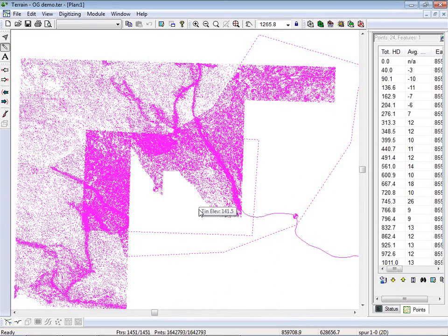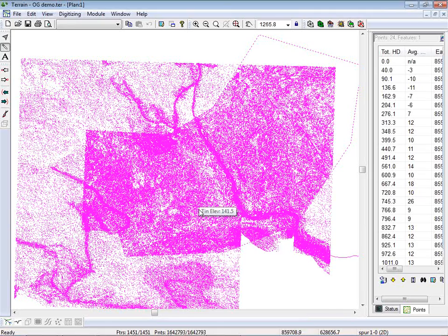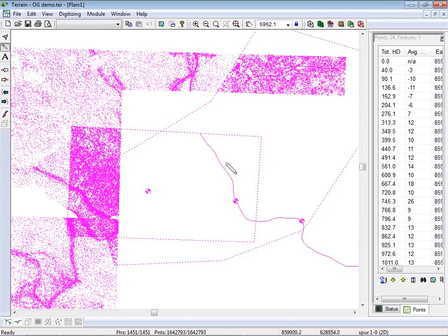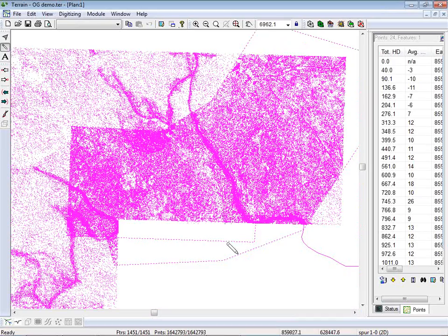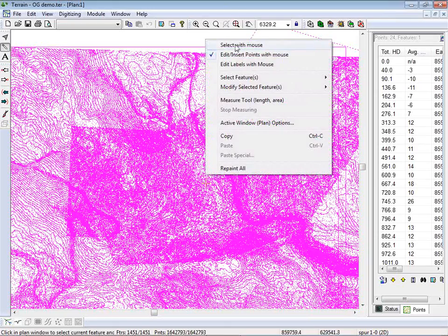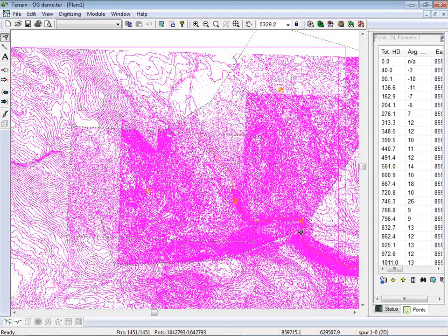Again, it depends how high you're flying and what instruments you're using and so on, but I was told even a few years ago that the vertical elevation accuracy was within 15 centimeters, which is amazing. So yeah, even through trees, you get enough information to do preliminary design. Any other questions?